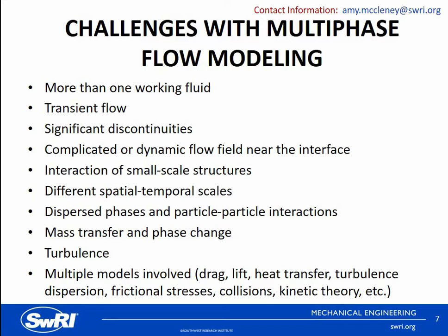And turbulence is a cascade process. As turbulence decays, its kinetic energy transfers from larger eddies to smaller eddies, which ultimately dissipate into heat through the action of molecular viscosity. Resolving the smallest eddies with a discrete mesh is unrealistic due to the computational resources that would be required. Instead, you have some models of the turbulent dissipative process that are employed.